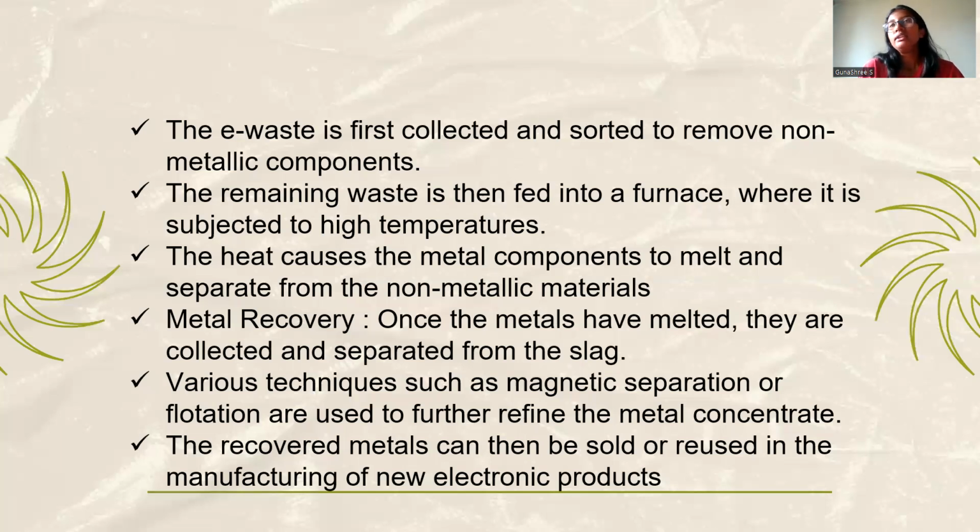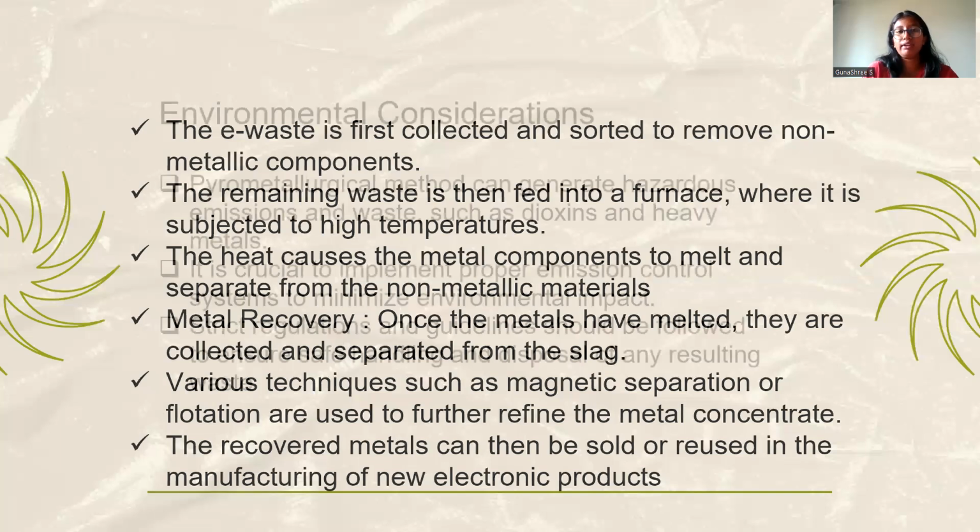In the furnace, the heat will cause the metal components to melt, and again it will get separated from the non-metallic materials. Metal recovery: once the metal is melted, it's collected and separated from the slag. Magnetic separation and flotation are used to refine the metal concentrate further. The recovered metals can be sold or reused in the manufacturing of new electronic devices.